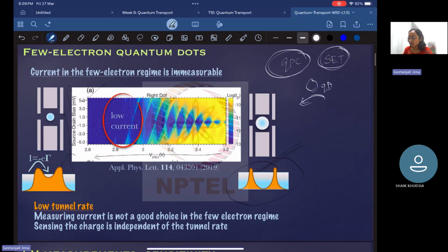So we are seeing this quantum dot, but we are measuring this charging and discharging event through this QPC or this SCT based sensor. Recall QPC, it's like a 1D constriction we have seen in detail in our previous live session. And SCT is like another Coulomb blockade device.